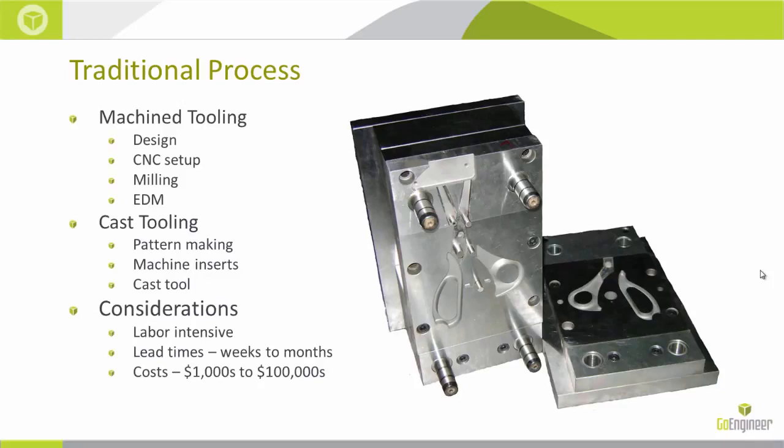You have design of the mold, but then you also have a CAM programmer who's going to be programming the CNC machines to cut those. And for mold type situations, the programming of those molds can take days, it can take weeks. If we're lucky, we're going to be milling it. All right, so we load it up to the mill machine, and if we're really lucky, it's only going to be a 3-axis process. But it's not uncommon to have 4- and 5-axis processes on these mold tools.